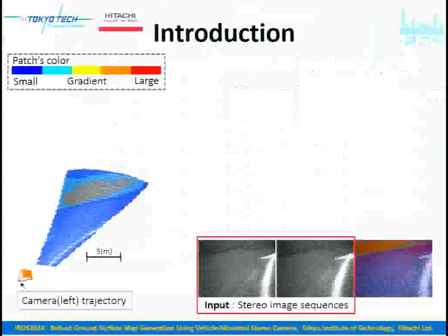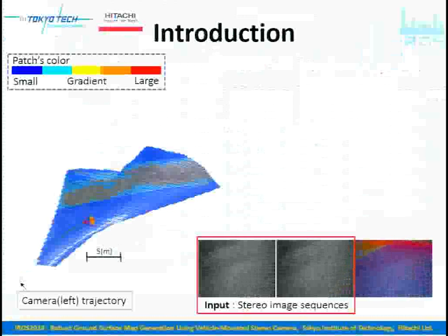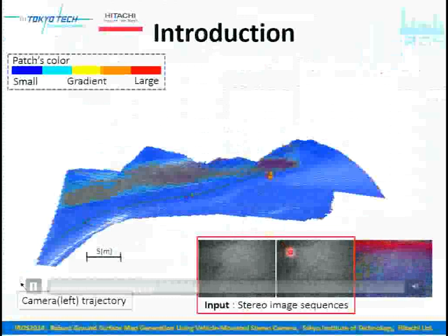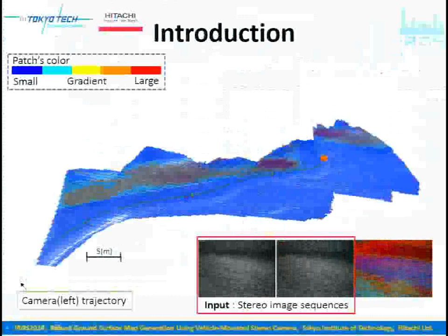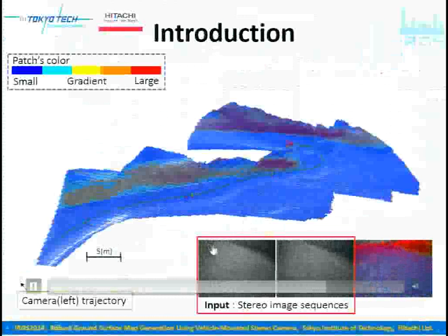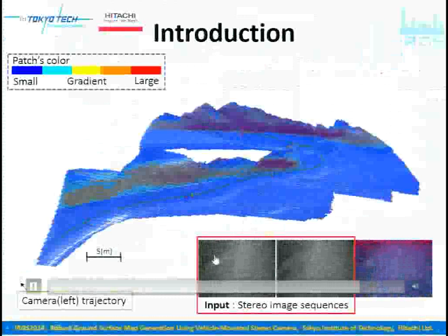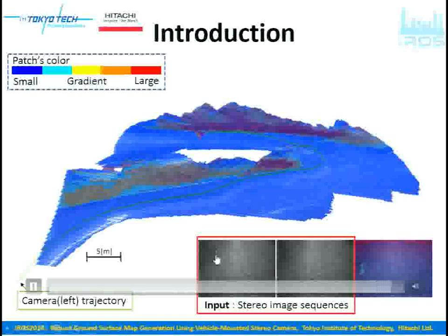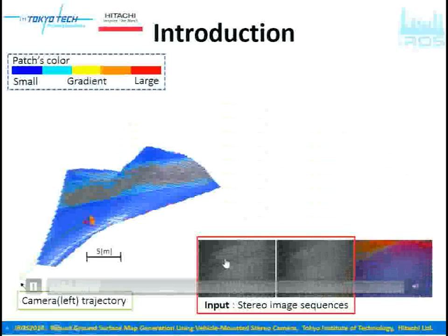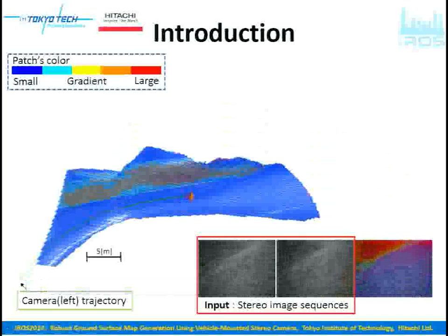Our goal is to build an off-road 3D ground surface map from stereo image sequence captured by nearly front-looking stereo cameras. At each time instance, we estimate 3D ground surface and camera ego motion. In our approach, the ground surface is represented by the vertex height of a regular grid mesh, which is friendly to mobile robot applications, such as traversable area detection and path planning.